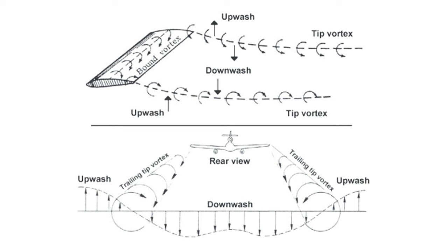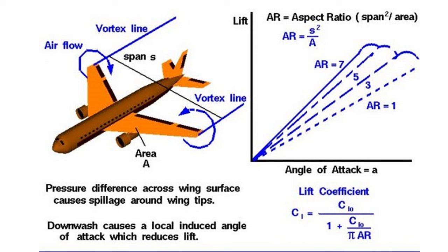For more on why this affects lift and not only just drag, see the first video in this series, which dedicates several minutes to lift distributions. Just for reference, I've included the equation describing this effect. You can see that the final lift coefficient is equal to the free stream ideal lift coefficient divided by a quantity that basically just means that the lift increases with aspect ratio. A classical representation of the induced drag phenomenon is called the horseshoe vortex system.